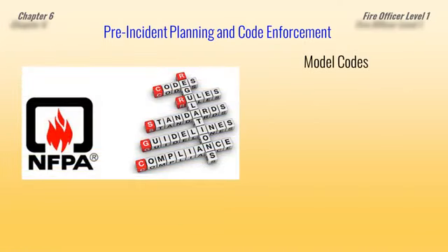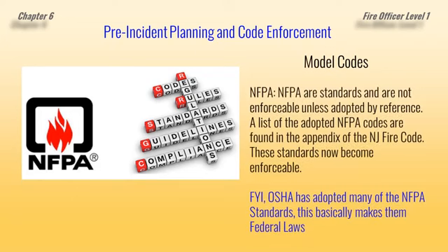Now we're going to take a quick look at model codes. So model codes, and again, we also talked about the International Building Code and Residential Code, Fuel Gas, Mechanical Code. Those are model codes, but in this case we're going to talk about NFPA, right? National Fire Protection Association. So the NFPA codes, even though they call them codes, they're actually standards, and standards are not enforceable unless they're adopted by reference.